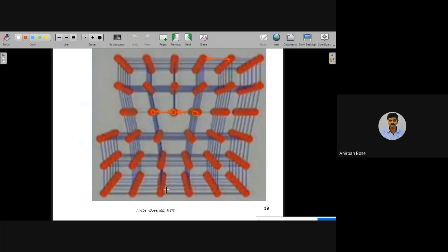If you observe here, you can see the regular part, that means the perfect part of the crystal. This is the distance. If the distance between the atoms is closer, then what will happen? That will create a compression. If the atoms are closer, then definitely the compression will take place. You are giving a push here and you have not cut all these bonds. So the distance between these atoms will be closer compared with the perfect part of the crystal. Yes, sir. They will be under compression.